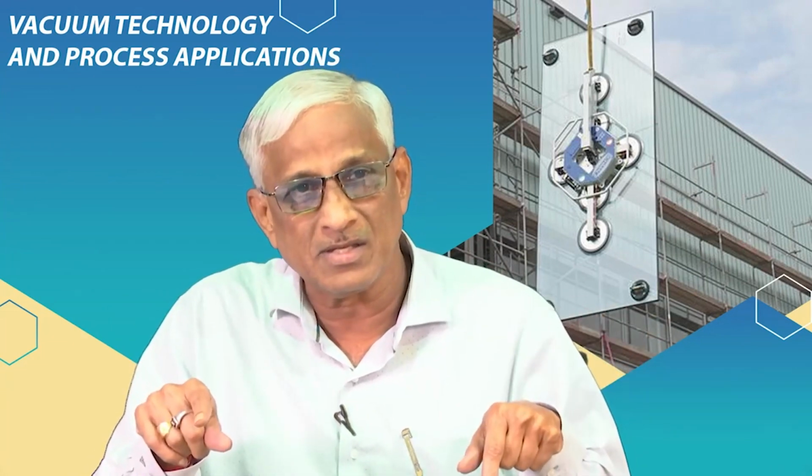This I want all of you to keep in mind, along with the working principles of these two important pieces of equipment, the magnetic deflection mass spectrometer and the quadrupole mass spectrometer, for understanding possible leaks and solving them to get better vacuum, as well as understanding the residual gas analysis. It may be intentional or background residual gas analysis, or to know the acceptability of that residual gas content to start your application process. So, this is a very important aspect.